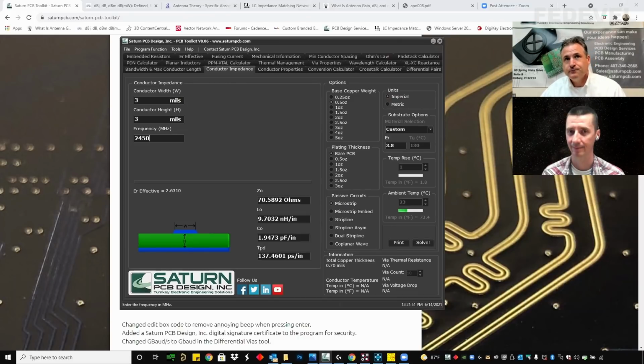I've tested them. A couple years ago, I used my VNA and put one port on either side of a board and measured the microstrip, and it was pretty accurate. VNA, is it the small device?